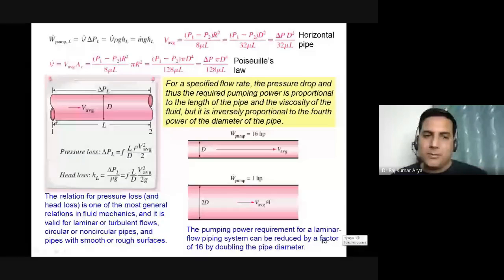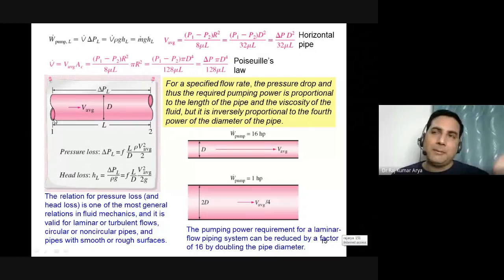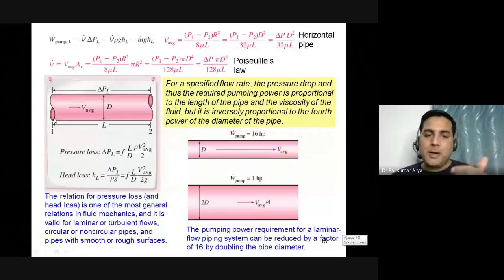So there is a mechanical efficiency of the pump that would be near again to 70%. So if the power of the pump is P, the power given to the fluid is P multiplied by electrical efficiency multiplied by mechanical efficiency. That would be the power delivered to the fluid. Fine.